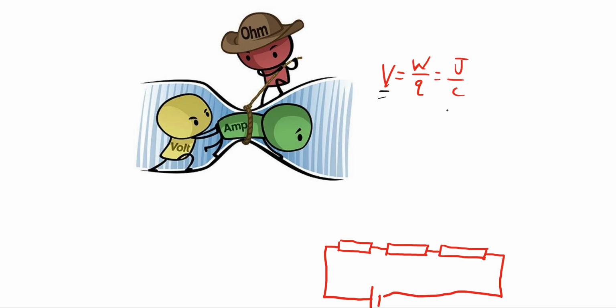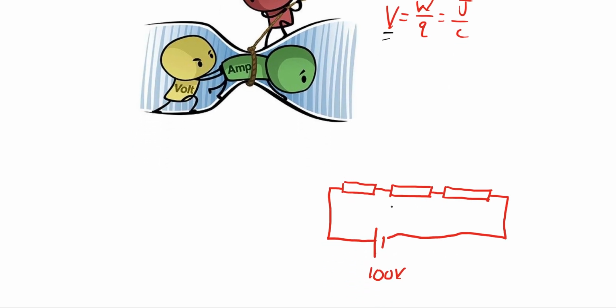And so if I take a device and I have a circuit and I measure the electric potential at a certain location. So I'm going to measure my electric potential here. And I see this is the 100-volt battery. I'm looking at the path of conventional current that's going around this way. So I've not run into any device that wants to use any of that energy yet. So no work has been done. So my electric potential at this point is still 100 volts, or 100 joules per coulomb of charge at this location right here. Then there's some work that happens.